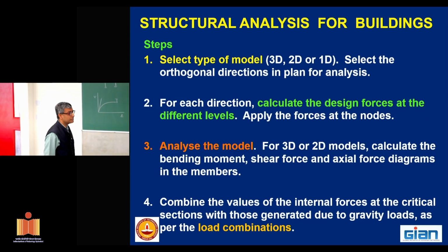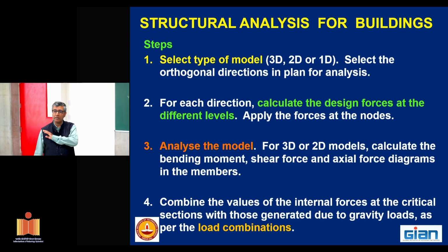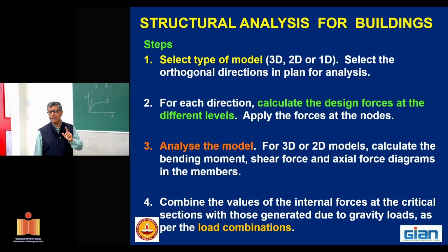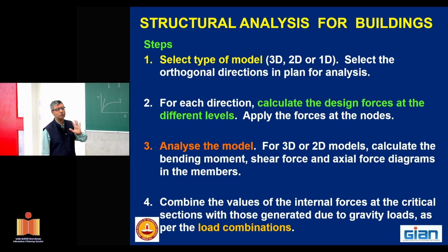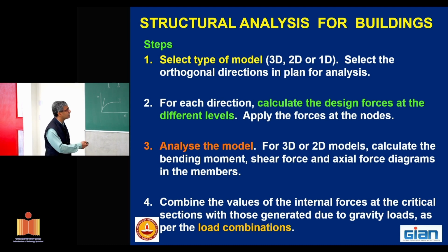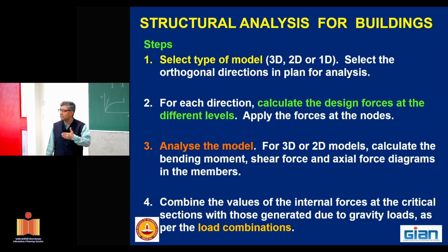Now, whenever you are doing a structural analysis, it's not that you directly jump into a complete three-dimensional model. No, you can do some preliminary analysis based on even a stick model or a two-dimensional model. It means you select a type of model. And for each direction, say along the X direction or Y direction, I need to calculate the force, wind or earthquake. Then analyze the model. Analysis means we are trying to find the internal forces, which are bending moment, shear force and axial force. And we are combining the effects of the gravity load as well as the lateral load.